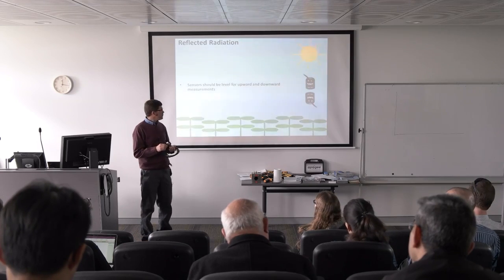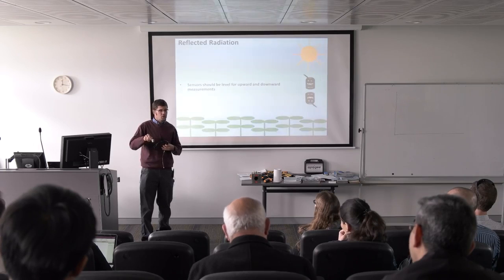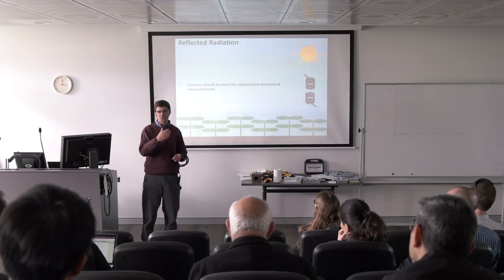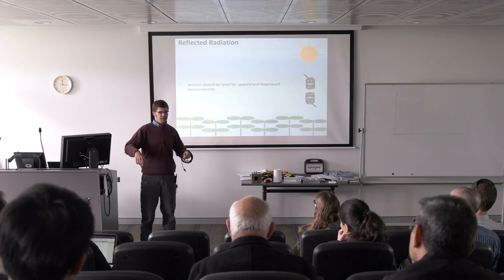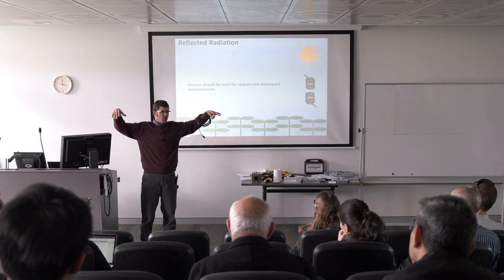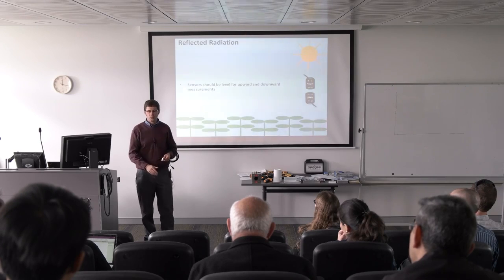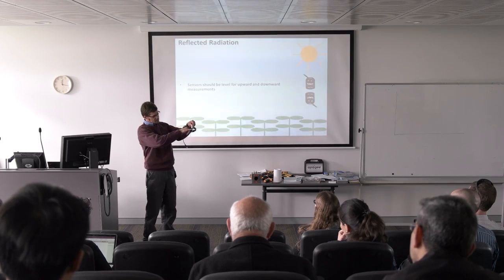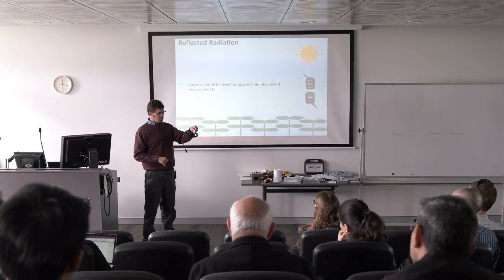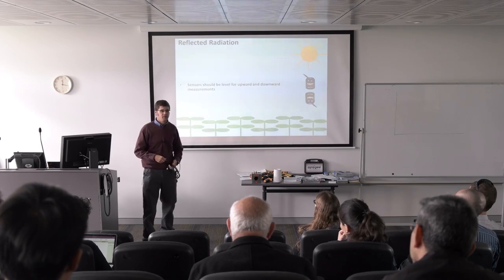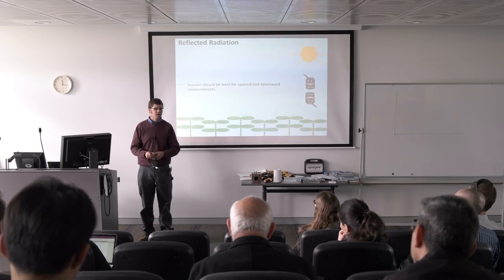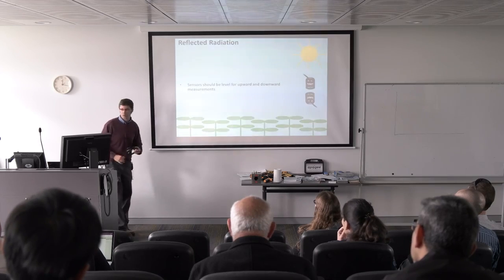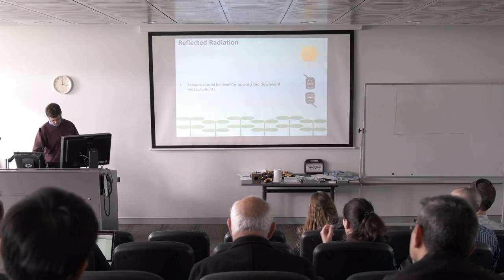The reason it's important to make sure the downward one is close to level as well is that in a place like Logan, Utah, where Bruce and I come from, it wouldn't matter that much because the entire valley where we live is surrounded by tall mountains. But in places where it's flat, when the sun first comes up over the horizon, you want to make sure that the direct sunlight doesn't hit the diffuser. And if it's tilted a little bit one way or the other, in the early morning or late evening hours, you might actually get some direct sunlight hitting the sensor that's not reflected from the surface. So you just want to be careful that you level both sensors.